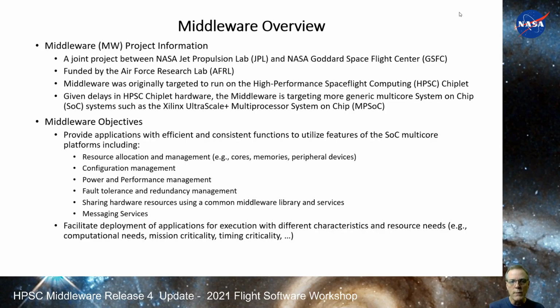The objectives of the middleware include providing applications with efficient and consistent functions to utilize the features of SoC platforms, including resource allocation and management, like the different cores, memories, and peripheral devices, configuration management, power and performance management, fault tolerance and redundancy management, sharing of resources using a common middleware library and services, and finally messaging services.